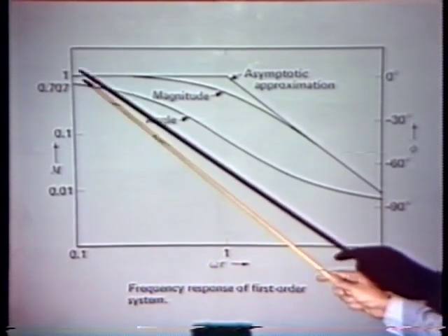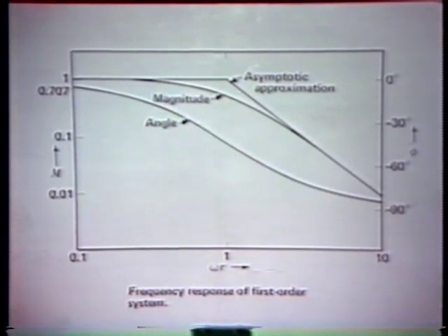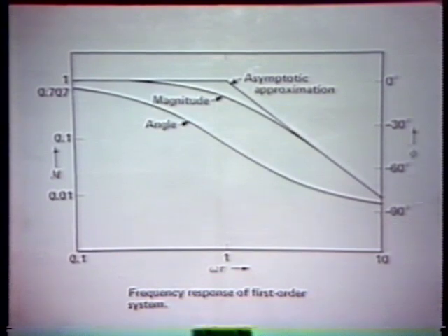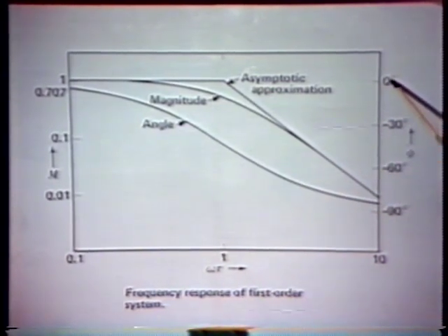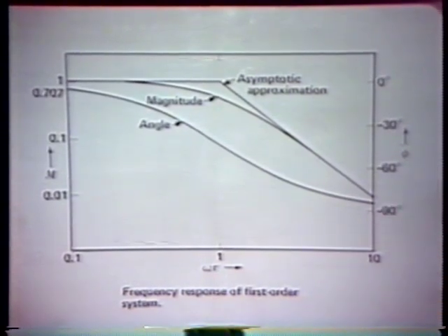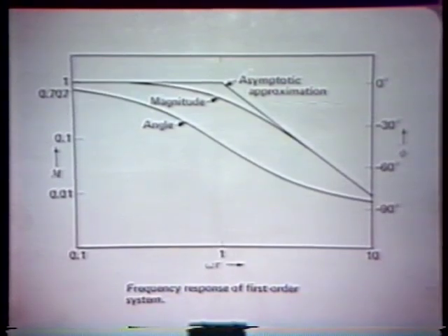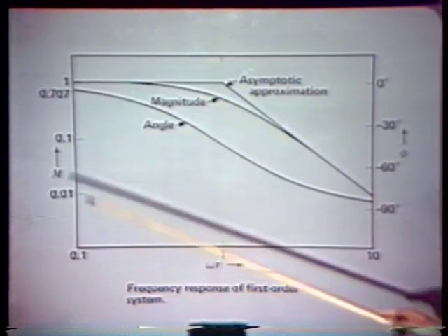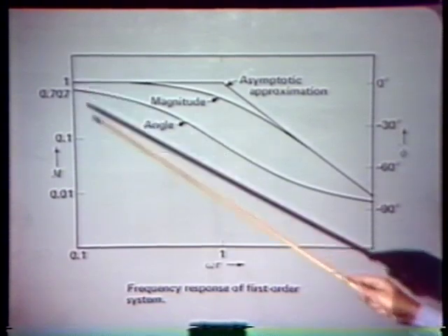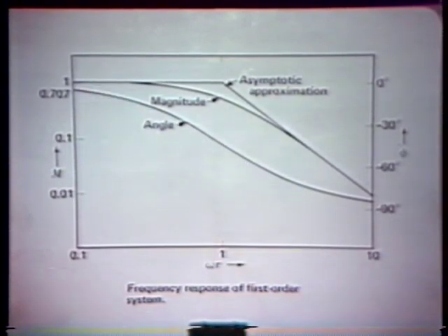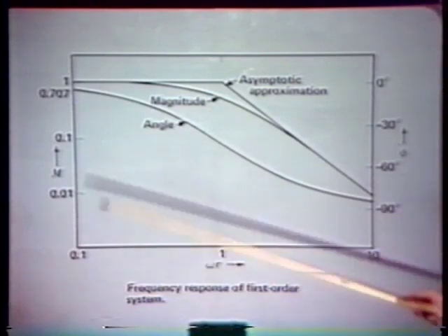So we do plot the magnitude, and we also simultaneously show the angle associated with our transfer function for, of course, sinusoidal steady state excitation. And here we have the angle scale over on the right-hand side going from 0 degrees to minus 90 degrees. The magnitude of our simple first-order transfer function is normalized to unity. This would assume in the expression that we had earlier that 1 over f naught was equal to 1. So we're plotting simply the magnitude of 1 over tau s plus 1.